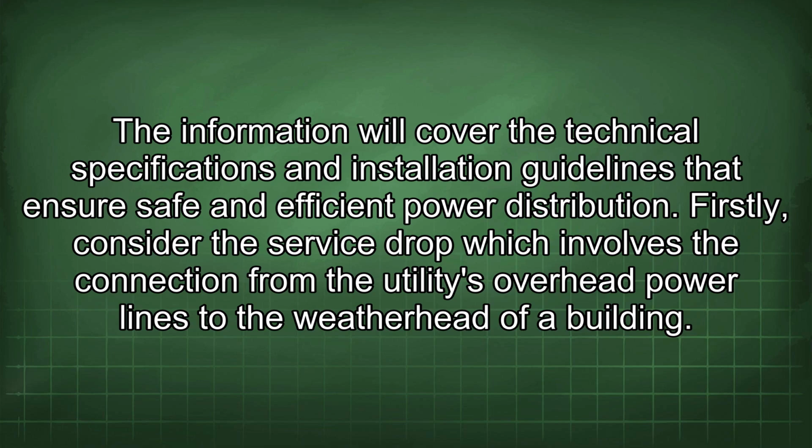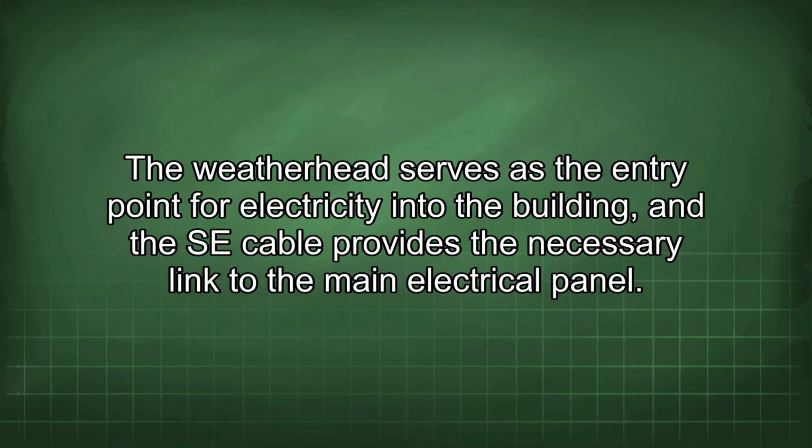Firstly, consider the service drop, which involves the connection from the utility's overhead power lines to the weatherhead of a building. The weatherhead serves as the entry point for electricity into the building, and the SE cable provides the necessary link to the main electrical panel.